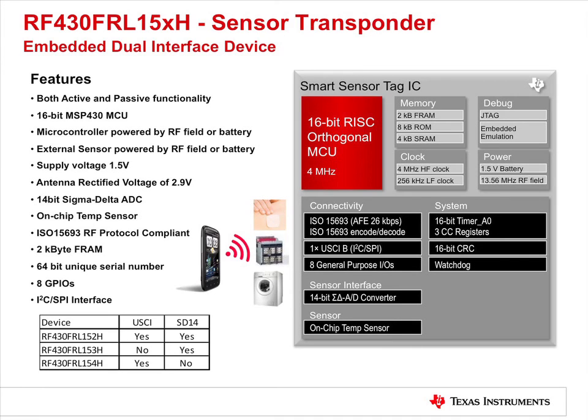It has an embedded application code in ROM which manages the RF communication and sensor readings and provides the ultimate configuration possibilities for the device. Developers can configure sampling rates, measurement thresholds and alarms, and much more. The available universal FRAM memory allows data storage of the sensor measurement data as well as the extension and adjustment of the integrated application code according to the application requirements.